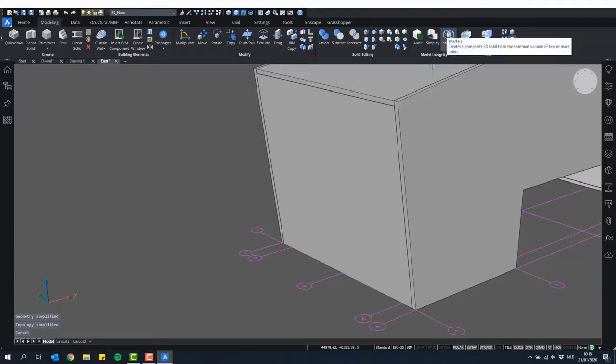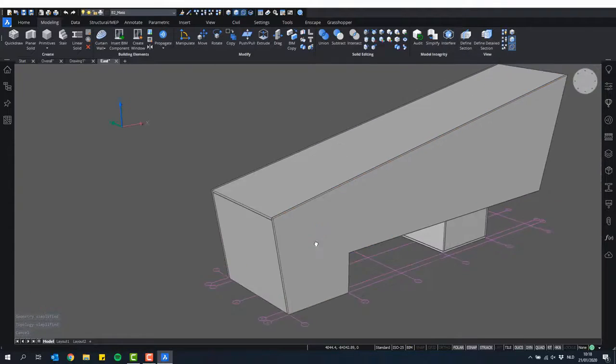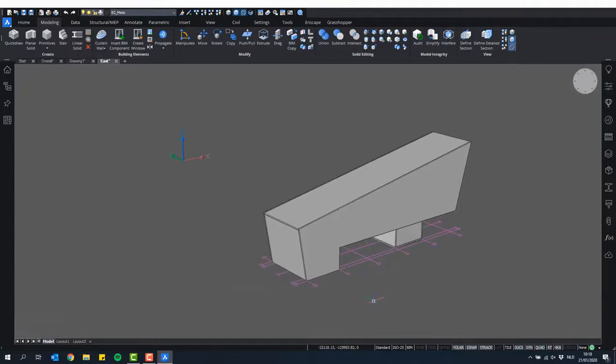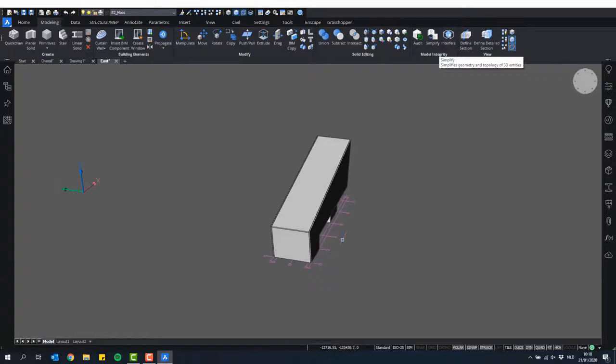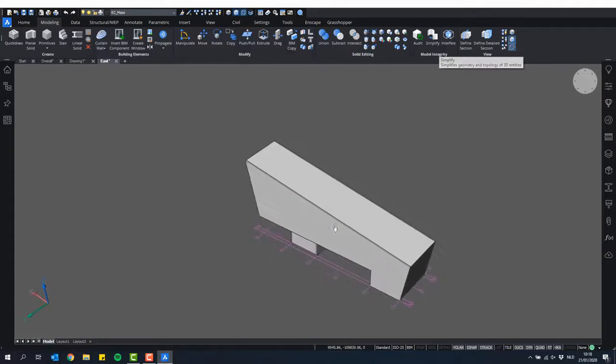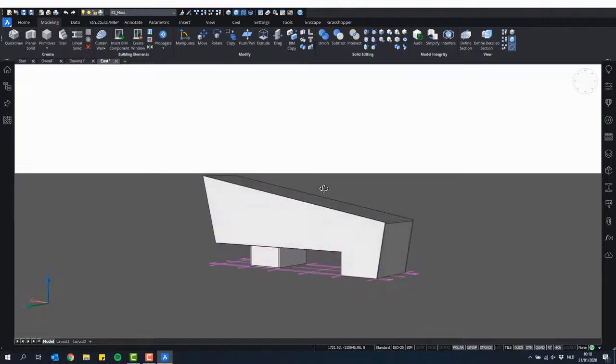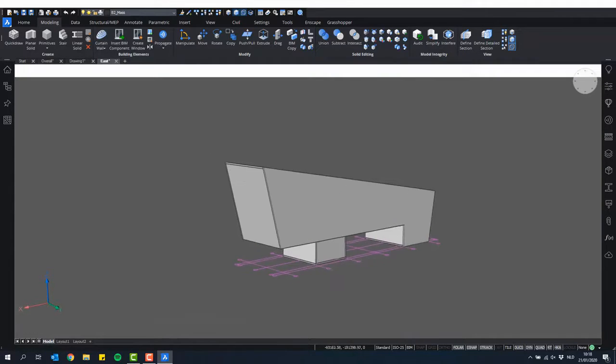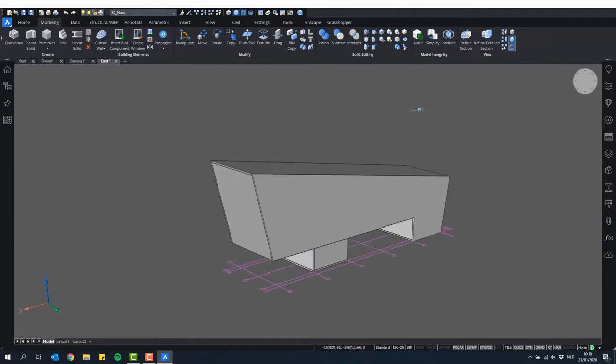And Interfere is basically a very basic clash detection. So you can quickly check, if you are modeling and you see that maybe there's some problem, like 2 objects clashing, where those clashes are and then solve it manually. So I always recommend using these tools from time to time, especially if you're new to modeling, because there are plenty of things that can go wrong.